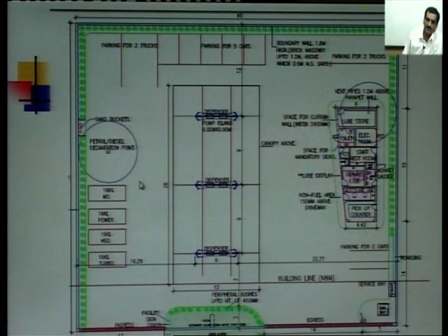BM pit means entire brick masonry is constructed along the walls, and then an underground tank is lowered down into that pit, and within that pit you have sand all around, and then we are going to have an RCC slab on the top, plus a cutout for having that hole from where you will be having that filling and decantation point and that kind of things.